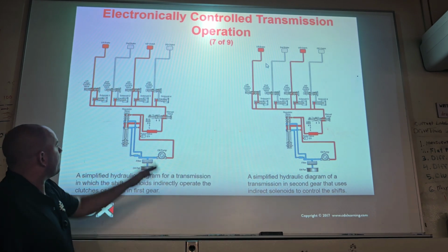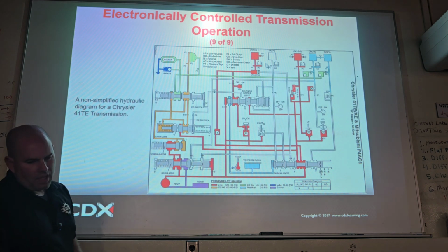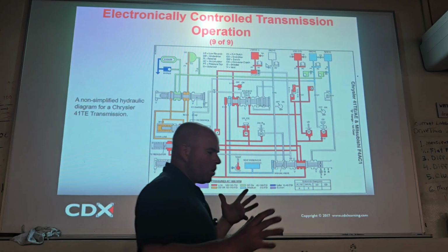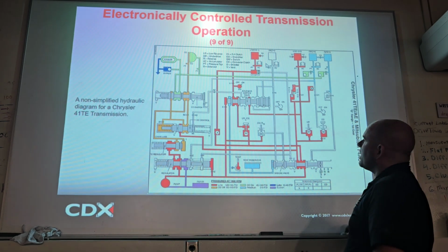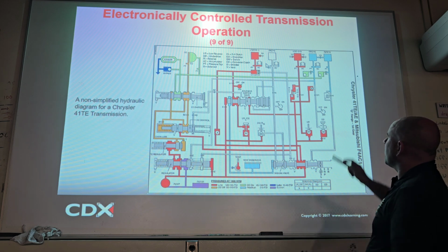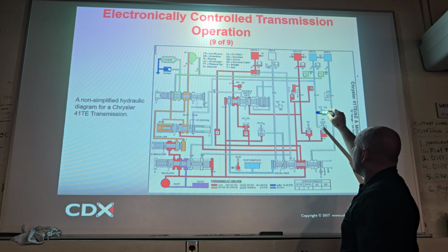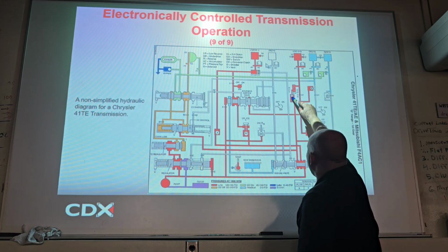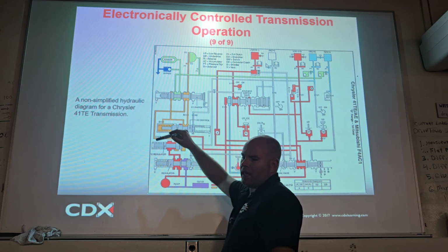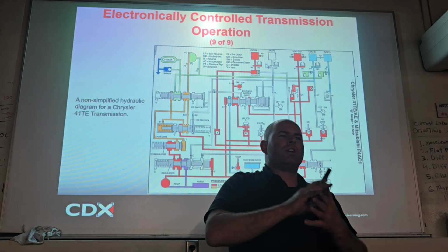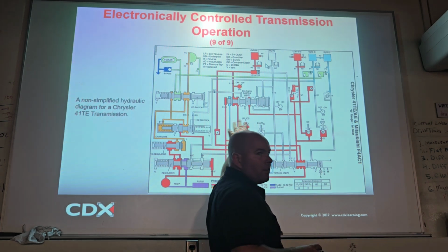And so this is just showing you first, second, third, and fourth using the relay valves, the bigger shift valves. Similar. This is just showing you a more exploded view of, let's say, for example, you had that clutch up there that was failing on you. You'd look at this diagram and you could trace it, every valve, everywhere it goes, right? Because if that clutch continues to fail, it may be because it's not getting enough pressure because it has a leak somewhere. So you'd have to troubleshoot all these things and see, is it leaking anywhere, right?